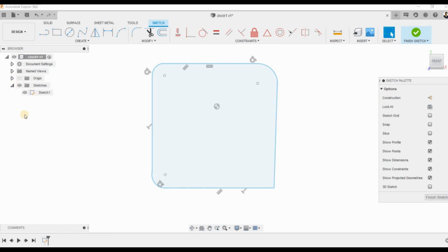Let's see how it is being shown here. So this is our sketch 1. We do not see a lock symbol over here. This means that this is not fully constrained. For learning sketch tools, I might not be able to constrain all the sketches just to save some time. But for this one, we are going to use constraints and dimensions to fully lock the sketch, or to make this sketch fully constrained. Now, let me start dimensioning this. It's a good practice to dimension it as soon as you start drawing your first entity.